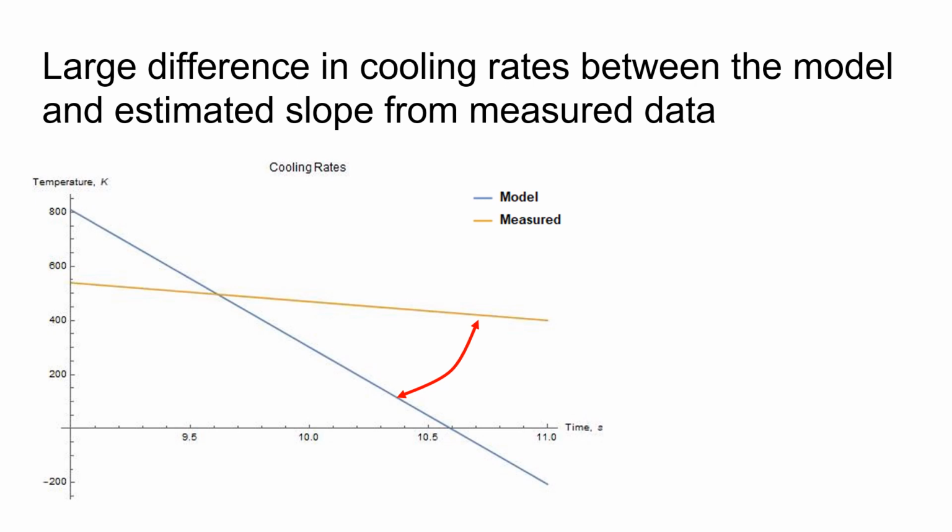This variation could be explained by data that was not captured fast enough. For example, our thermocouple only took data every 1 second. Taking data in smaller increments could show behavior that resembles our model a little bit closer. Another reason for this variation could be that our model is not yet fully refined and needs to be further examined.